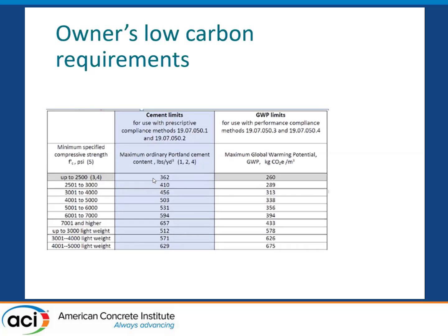Now, when we limit the amount of Portland cement that could be in a mix, we can't just generically say this, because it depends on the project and the application of the concrete. For example, if it's precast, it may have high Portland cement amounts initially, but because of the ability to make it thinner and so forth, if we just use these numbers, it's not going to work out for everything as a whole.